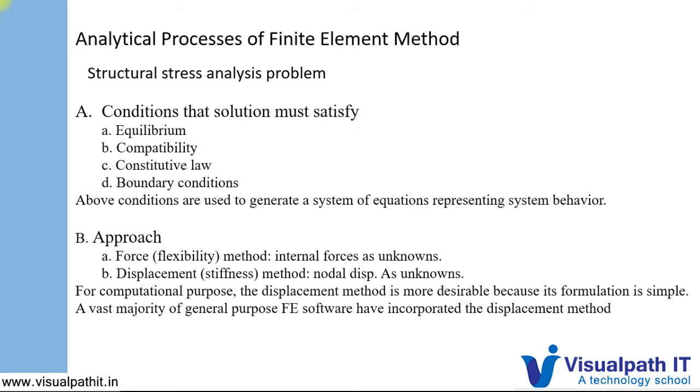We define a system with known forces. Then our displacements become unknown. We don't know how the system is responding. To solve that, we use the displacement method, where the nodal displacements are the unknowns, and we solve for them.